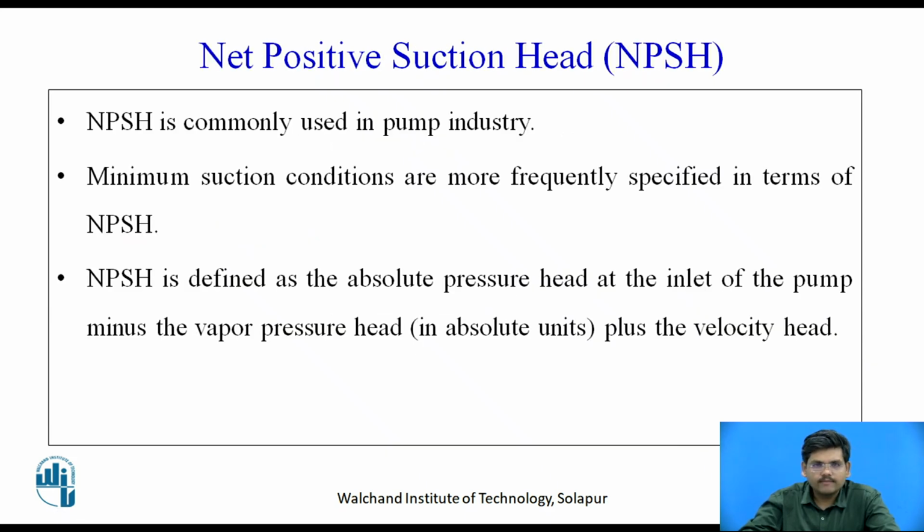net positive suction head. Now as far as net positive suction head or NPSH is concerned, it is a commonly used term in pump industry. So minimum suction conditions are more frequently specified in terms of NPSH. The minimum parameters that are required to have the desired suction and delivery of the fluid is specified with the help of NPSH. Now we can define NPSH as the absolute pressure head at the inlet of the pump minus the vapor pressure head plus the velocity head.